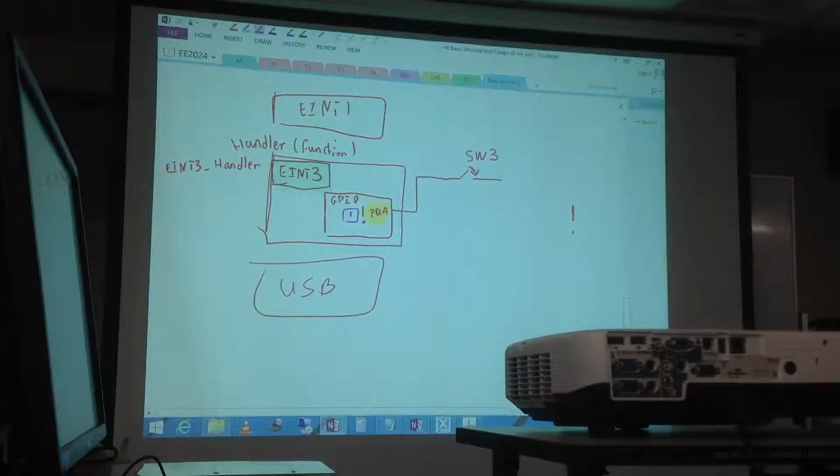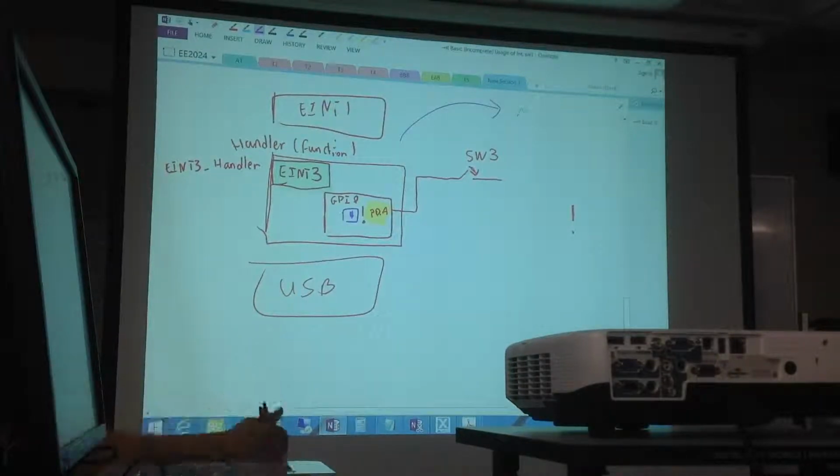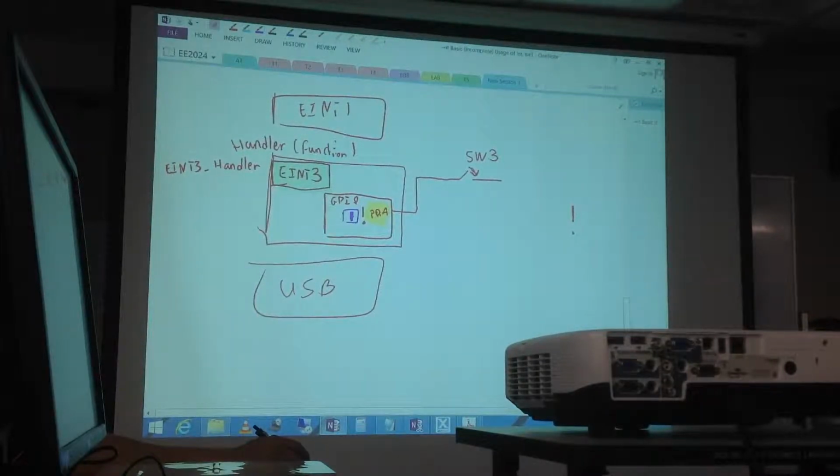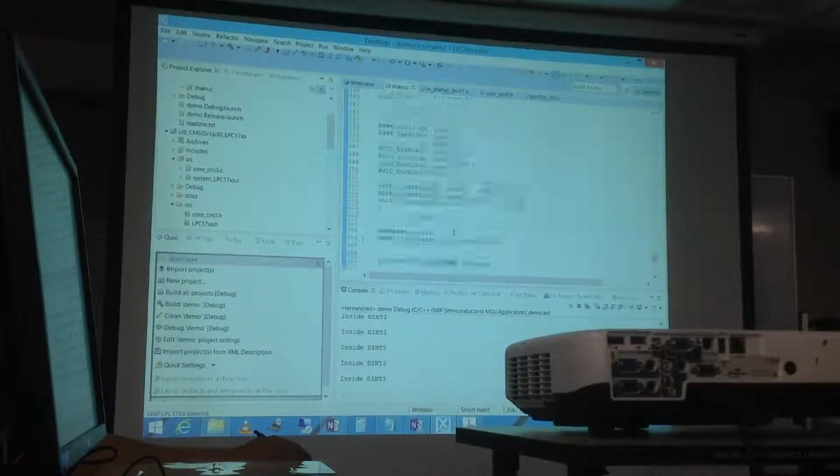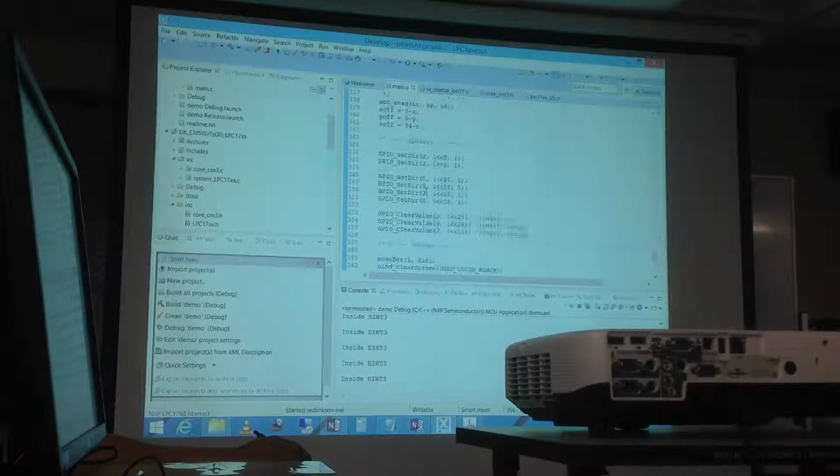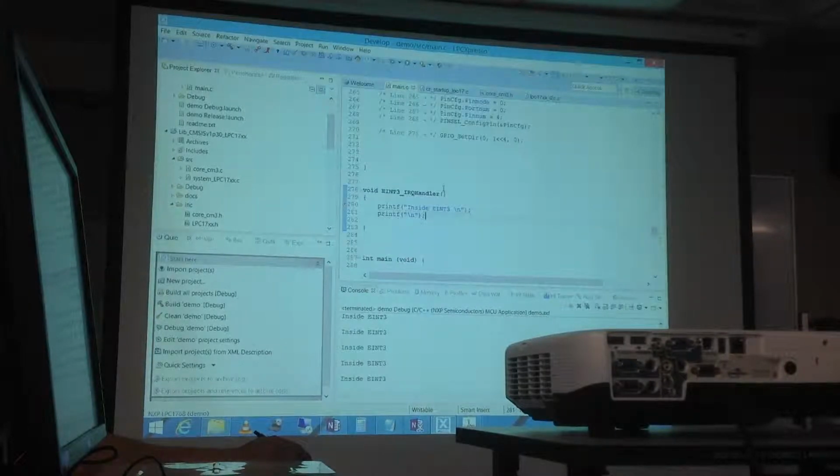So it means after you have printed your things, it is still 1, it has never changed. You have printed something, you went back to your main program. Again, the interrupt is detected because it is still 1. So it prints something again, it goes out, it's still 1, it still prints. So this goes on forever. So this means if you want it to happen just once, you need to make the value become 0, right? So let us include a clear instruction here.